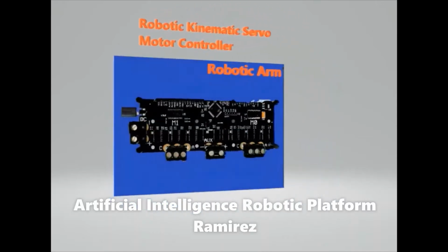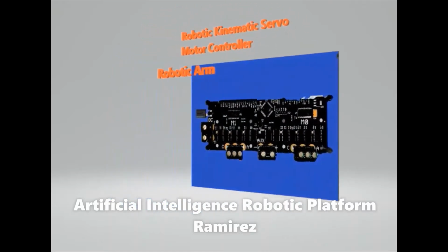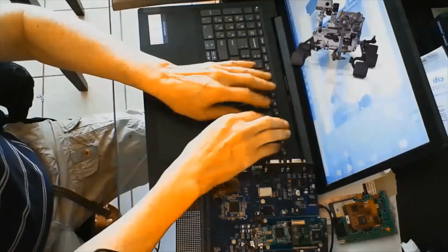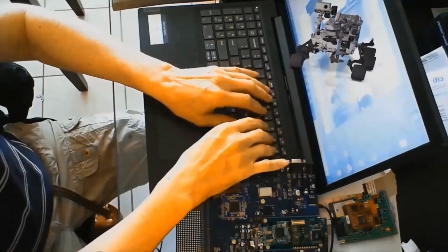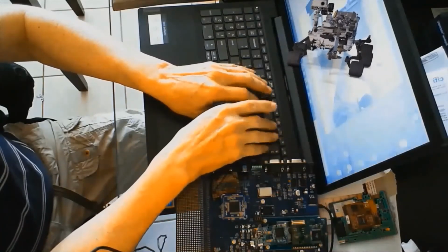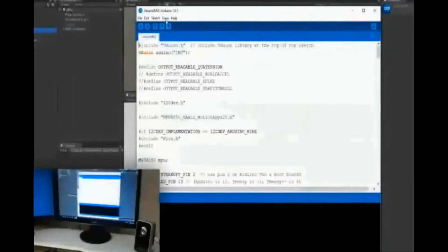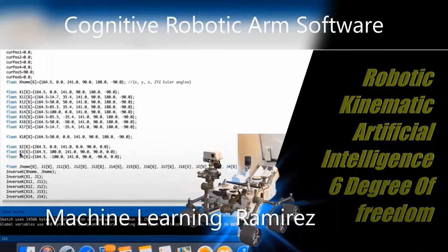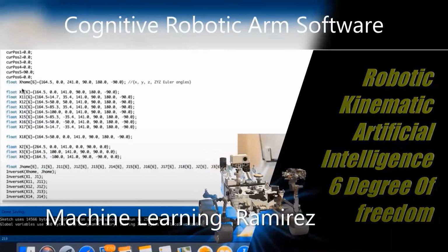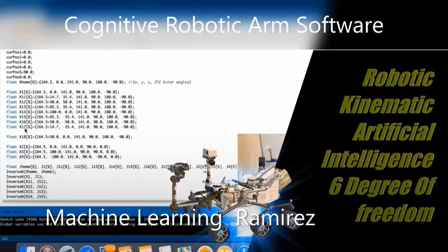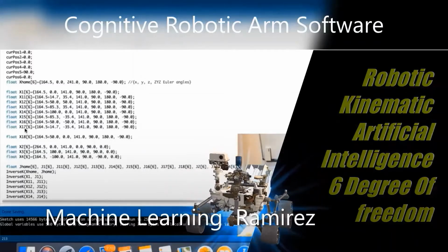Using the hexagonal plates, instead of having one possible setup, we can imagine many, where the top plate, indicated by the 3 red anchor points, can be smaller or larger than the base plate. The motors can be rotated inwards or outwards, and the same for the servo horns.